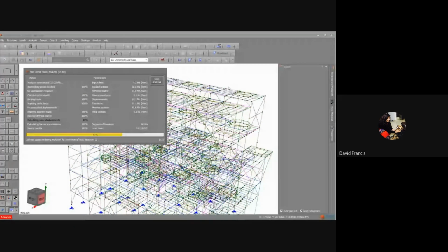If you're not aware of P delta, this is when a member gets displaced. It shifts from its normal position, and there is the overall deflection versus the load, and then there is the internal deflection within the member itself, which is the little P delta. And that is important to be considered in designing the structures. So I think this takes about 49 seconds to complete. So we're pretty close, 43.